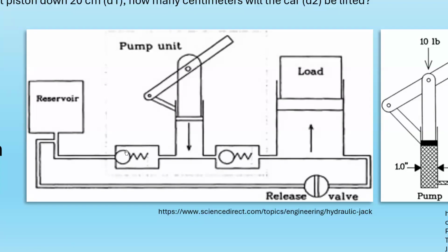What do we have here? We have a blockage, and this suggests there's a spring. It's a spring-loaded device, so that thing here is closed by default, and so is this if nothing acts on it. With the reservoir, there's no pressure in the reservoir, you can just top this thing up. Did you ever have to top up the brake fluid in your car? Well, here's your reservoir. There's no pressure, you can just unscrew this top and take a look at it. There's just enough fluid for us to work with.